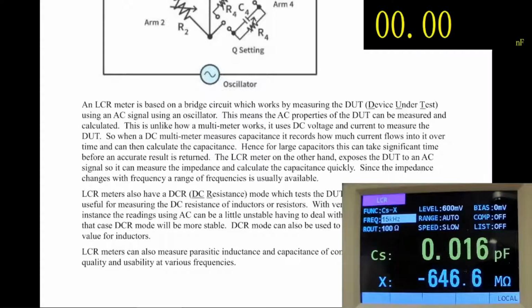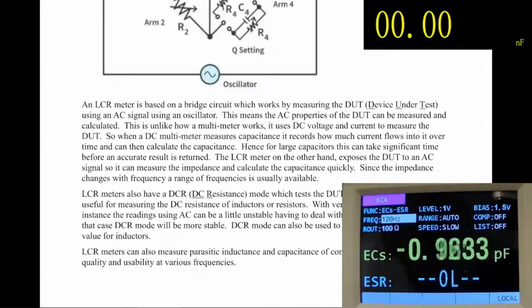And this is an electrolytic, so in actual fact let's set it to proper electrolytic mode. And you see it immediately came up, within a second, with 3223, something millifarads, 3236 microfarads, which is what that thing is, and it's got a good ESR, as you can see, 0.08, which is well within range, so this is a good capacitor.